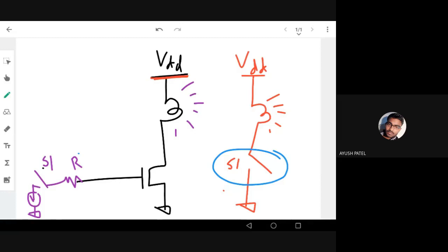One advantage of this circuit is that the MOSFET circuit helps in isolation. We know that for a MOSFET there is no gate current. That is very important. Why is there no gate current? Because it is a metal oxide semiconductor, with an oxide insulator between the gate and the transistor channel body. So there is an insulator in between, so there is no current. So one advantage here is insulation. I'm getting insulation.